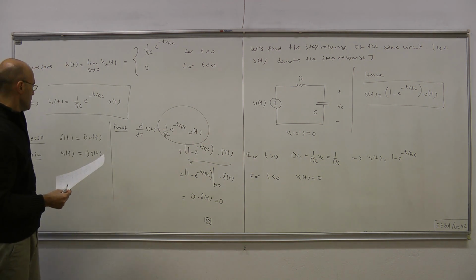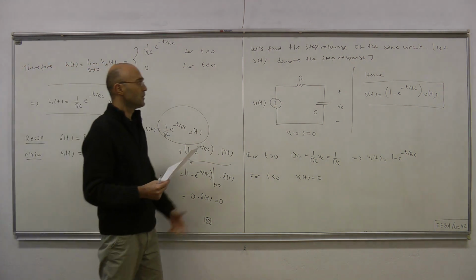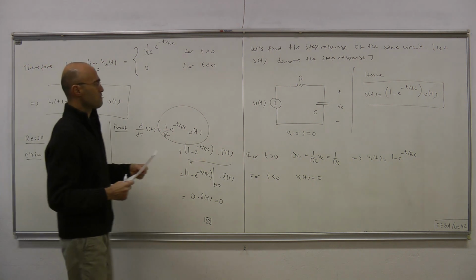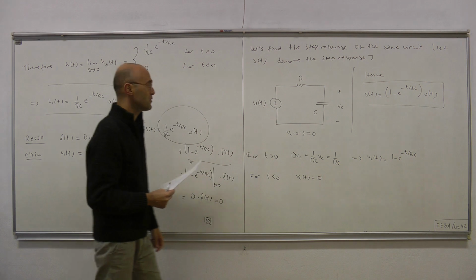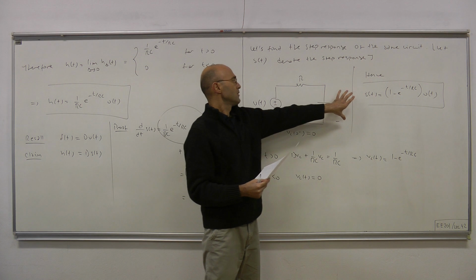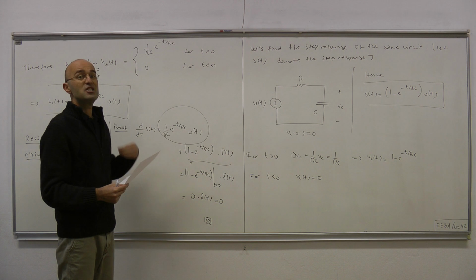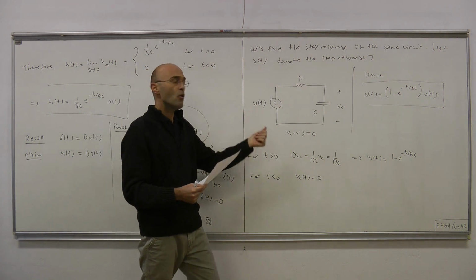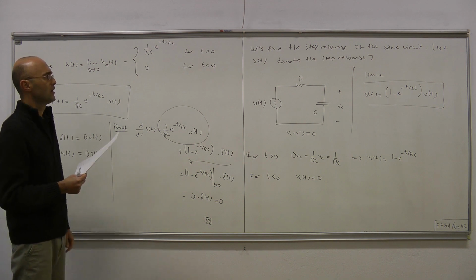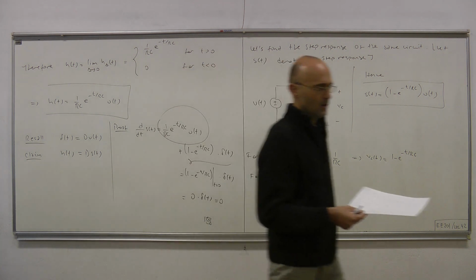Now, this raises the question: can we generalize this to more interesting situations? That is, we're talking about the zero state response. Suppose that for some input you have something at the output, zero state response, and then if you apply the derivative of the same input, do you obtain the derivative of the output that you recorded in the first experiment? The answer turns out to be positive.